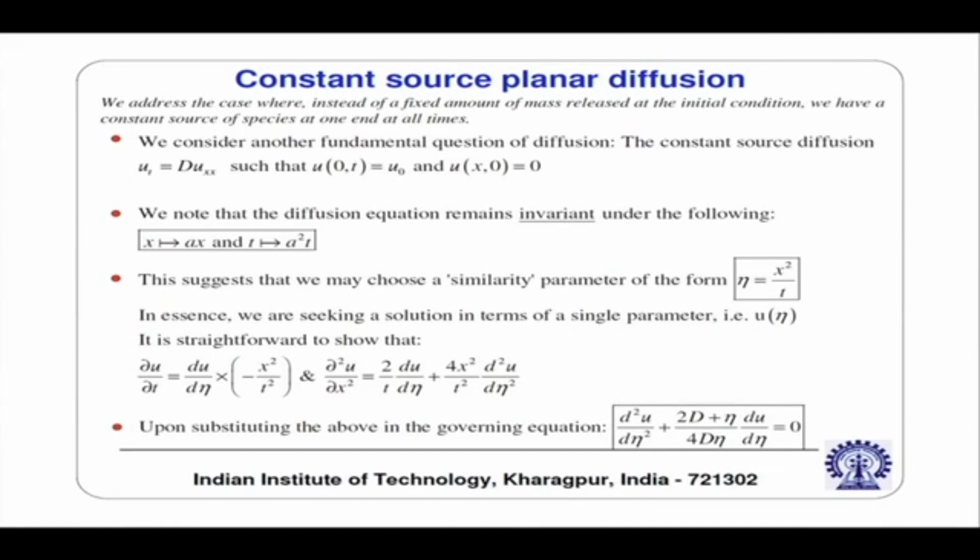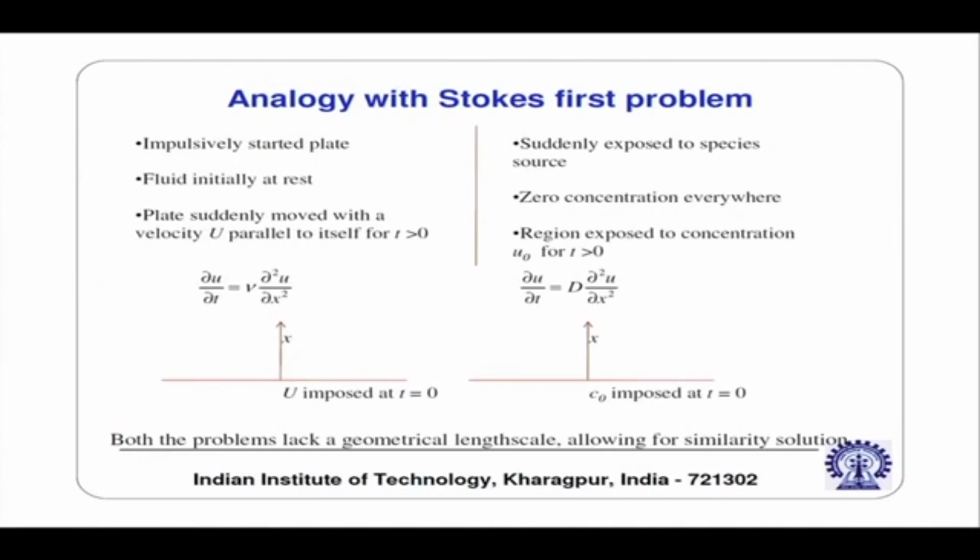You get this differential equation. So I have shown how you convert the PDE to this ODE, and then the analogy with the Stokes first problem, this I have already discussed. The Stokes first problem is an impulsively started plate: the fluid is initially at rest and the plate is suddenly moved with a velocity u parallel to itself for t greater than 0. This is the governing equation,